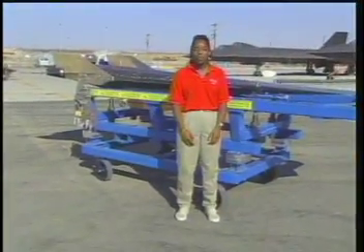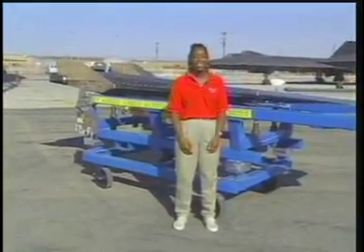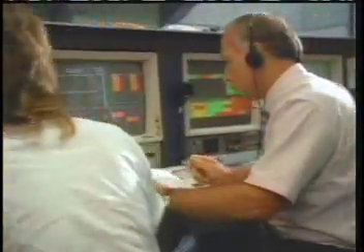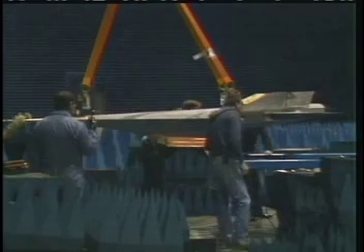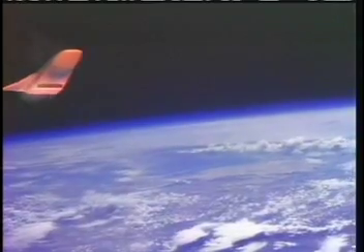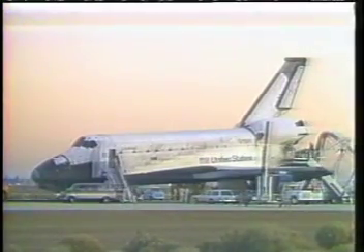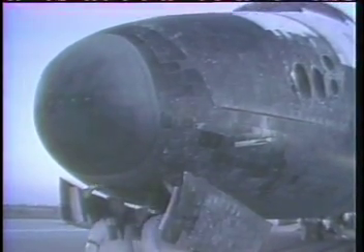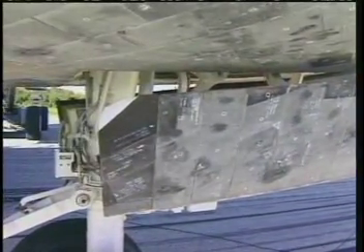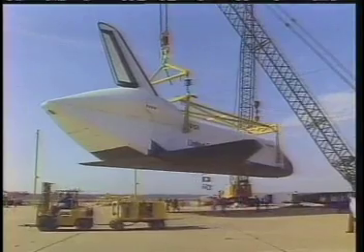In order to do this, we perform tests on the vehicle to ensure that the instrumentation system will measure the necessary data. We make sure that the control room is set up properly to record this data during flight. We also perform inspections of the HyperX during assembly and testing to ensure that the systems are operational and that no damage has occurred. You see, the HyperX has a thermal protection system, similar to the Space Shuttle. The exterior is covered with special tiles that allow it to withstand the high temperatures of high-speed flight. If any of the tiles were damaged, not only would the vehicle's structure be compromised, but the aerodynamic shape that we've tested during the design process could also be altered, and this could affect the flight.